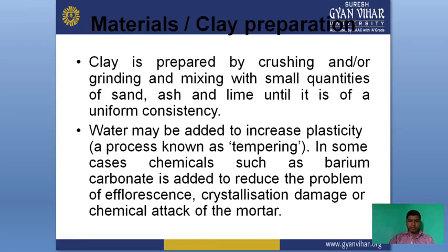Clay is prepared by crushing or grading and mixing with small quantities of sand, ash and lime until it is of a uniform consistency. Water may be added to increase plasticity, a process known as tempering. In such cases, chemicals such as barium carbonate are added to reduce the problem of efflorescence, crystallization, damage or chemical attack of the mortar.